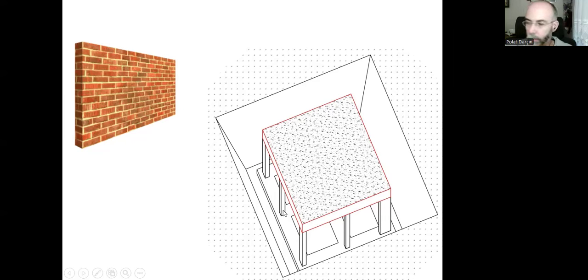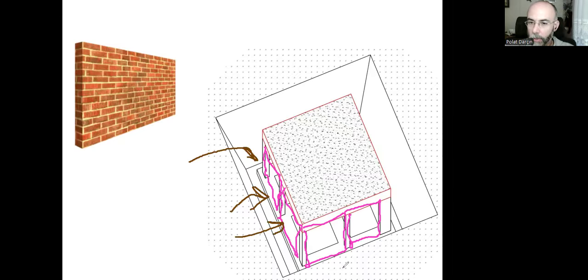So we can prefer brick walls. But as you can easily understand, when we place brick walls here in between these columns, so that we can have an empty area in the inside of this part for our basement floor, when we try to put all the earth back into this pit, the earth will create a certain amount of load, lateral load, pressure. And these brick walls, they won't hold it because they are not strong enough.